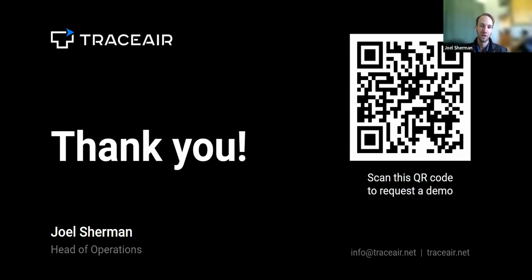So this is generally where we're going to have to make assumptions around what the elevation profile is whenever there's water on site. And this is where weather does impact when we're able to capture data, and the current ponding conditions or water conditions on the project. So we'll have to delay acquiring data until those have been drained, or make an assumption that in those areas where there is any ponding, the surface model is just going to be the surface of the pond. We can calculate what that surface looks like and then flatten it out, effectively saying this is what we think the earthen surface is going to be like.